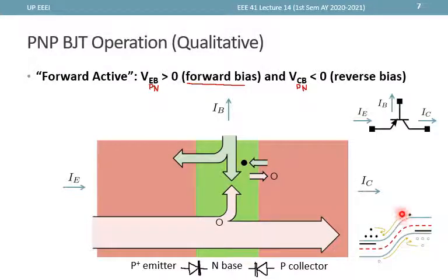And we want this current to be a small amount, and it is actually a small amount only since this one is reverse bias. And in this figure, the transfer of charges is actually represented here. So the reverse current is actually made up of the electrons from the P side to the N side, and of the holes from the N side to the P side.